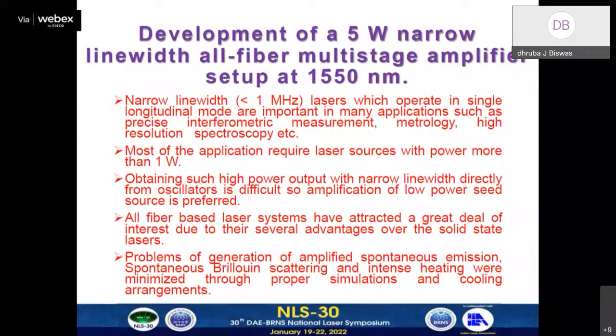I will be presenting on the development of a 5 watt narrow line width all fiber multi-stage amplifier setup at 1550 nanometer. We call a laser system having line width less than 1 megahertz narrow line width, and these systems are required in many applications, for example precise interferometric measurements, metrology, and high resolution spectroscopy.